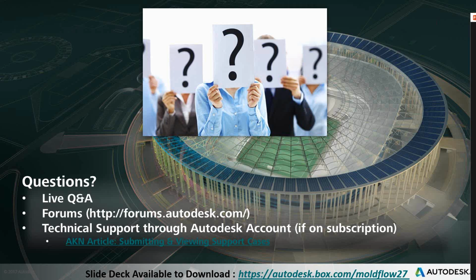But if you only have a single, say, Ultimate license, you can only run effectively two analyses at a time, then that DOE is going to take a little bit longer. Obviously your system configuration has a lot to do with that. So it really depends on how long it takes to run the analysis just on a single normal, say, fill-pack-warp, and then your licenses available and the DOE that you set up.